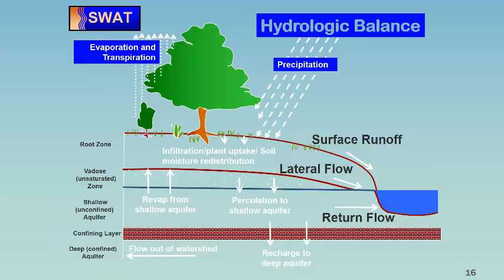right behind that is going to be a shallow aquifer. Like you see here, this is the shallow aquifer part. Shallow aquifers are typically between, say, 2 meters to 10 meters or so. Then you have a confined layer and a deep aquifer. So when there is a rainfall, that rainfall is first divided into runoff and infiltration.